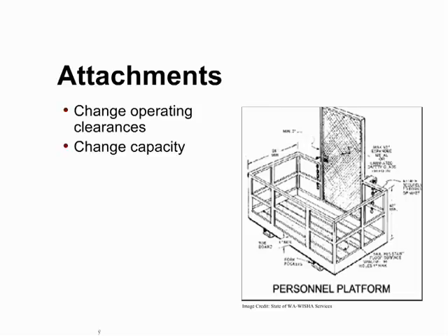For example, if the attachment weighs 1,000 pounds, then the capacity of the load you can carry is reduced by 1,000 pounds. Attachments usually change the stability and center of gravity of the forklift. For example, if an attachment moves the load away from the vertical face of the forks, that will reduce the maximum load the forklift can carry. Next, let's discuss the hazards of operating a forklift.